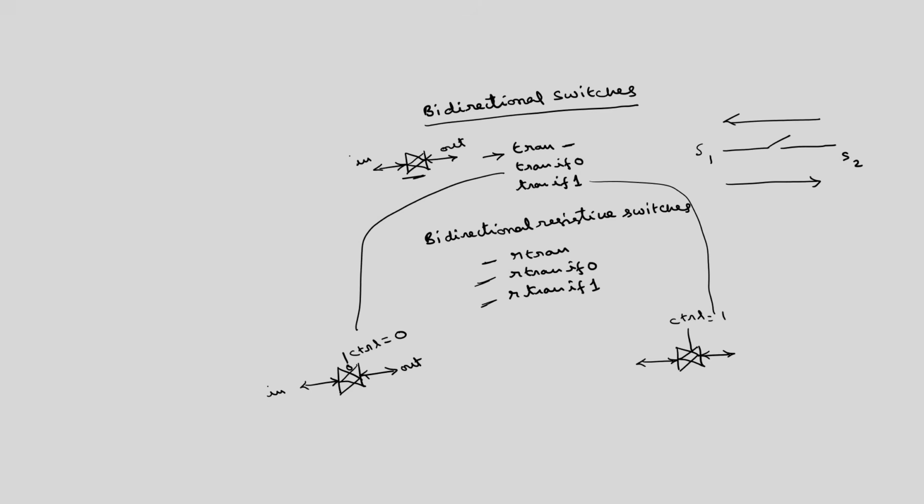Now there are some signal strengths. We can have totally 8 different signal strengths. As we know, in case of resistive switches, the signal level here is S1, and here is S2. Similarly, if I pass this S2 to some other resistance giving S3, then in terms of signal strength, S1 is greater than S2, and S2 is greater than S3, because S1 corresponds to some voltage level, and there will be some voltage drop across this resistance.